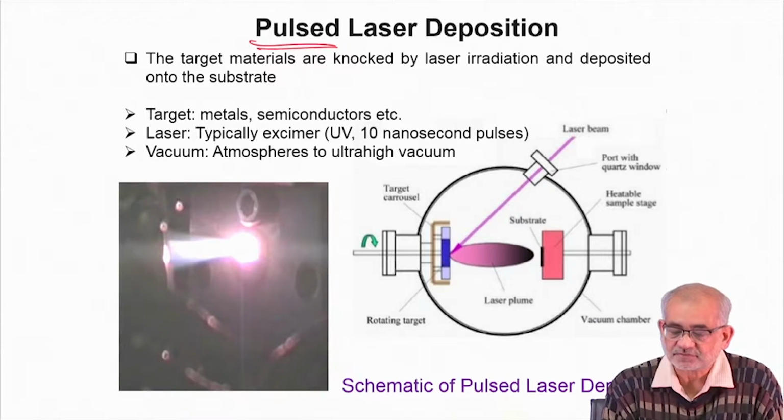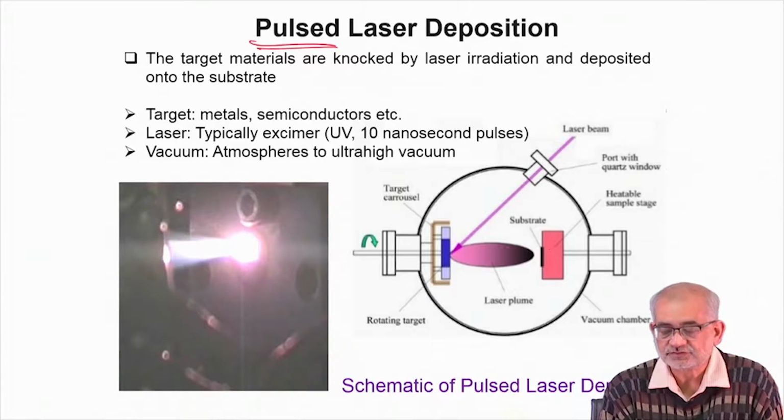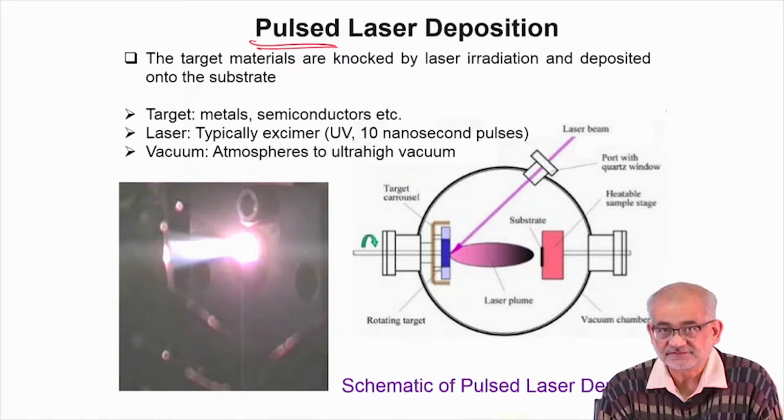So in other words, the composition of this target can be completely tailored the way we want, and we use a laser beam which will hit this target and immediately vaporize a part of it, and that vapor will travel through this particular distance, and by the time it reaches the substrate, it undergoes a change of state and then either condenses directly from the vapor or condenses in the form of semi-molten splats.